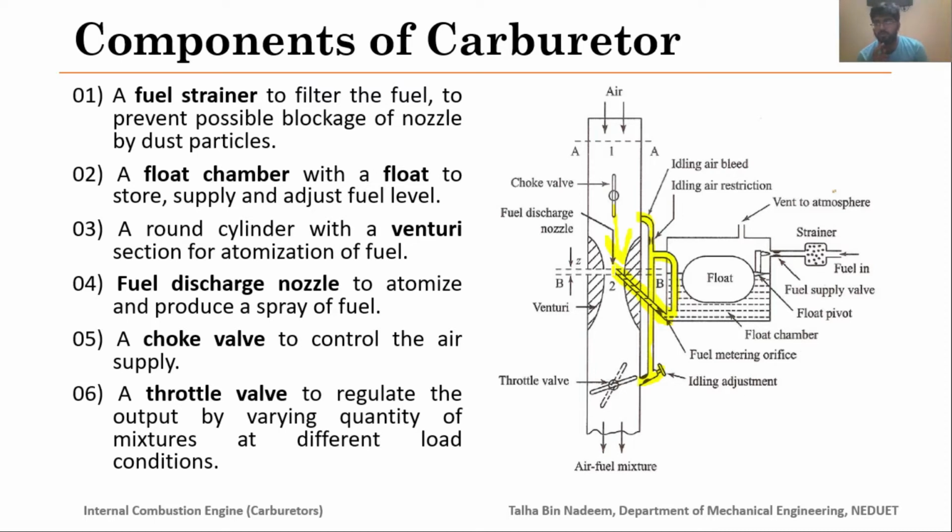So we would have a lean mixture, but during the idling condition we basically require a rich air fuel mixture. In order to overcome that, we have provided this idling system.